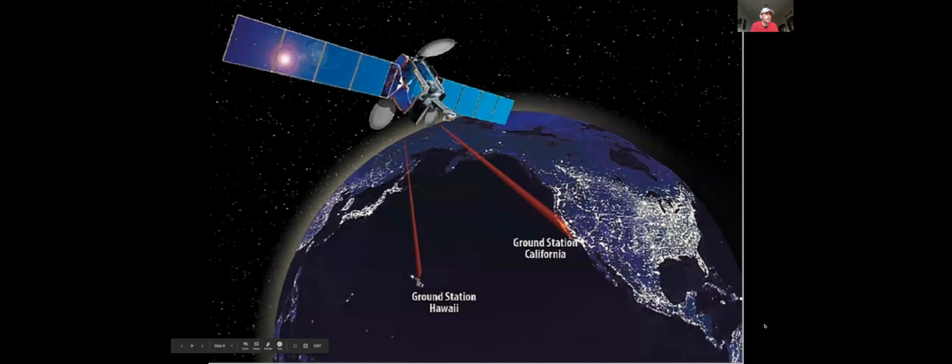And it does have to interact pretty heavily with the other subsystems. So oftentimes that interaction is handled at the level of the flight software, because you need to know where you are so that you can figure out how to point your antenna at the ground station when you want to turn on your radio and send the packets down that have that juicy data.